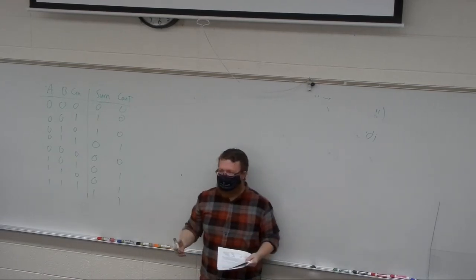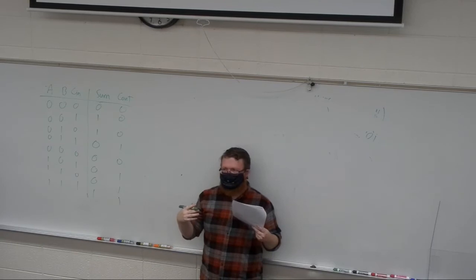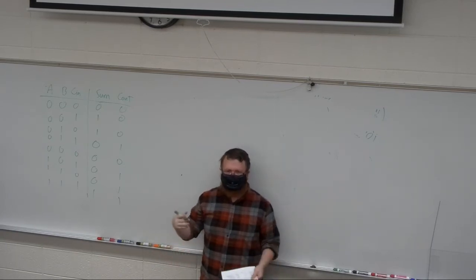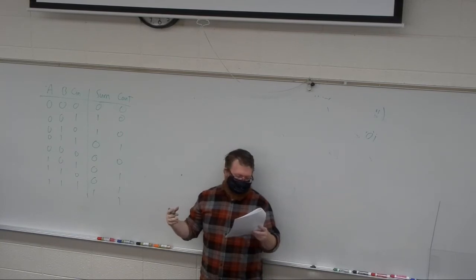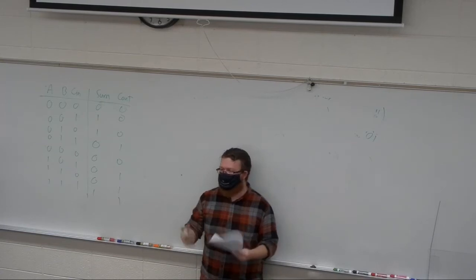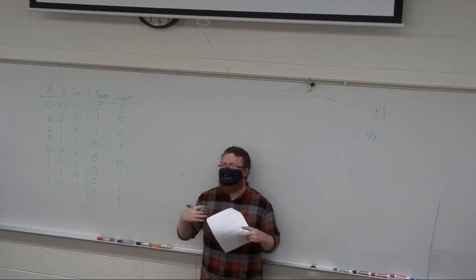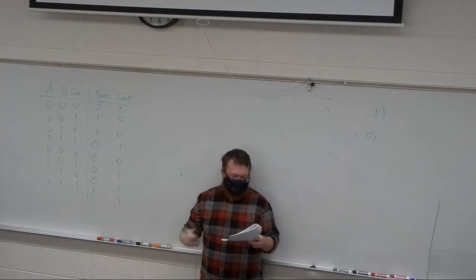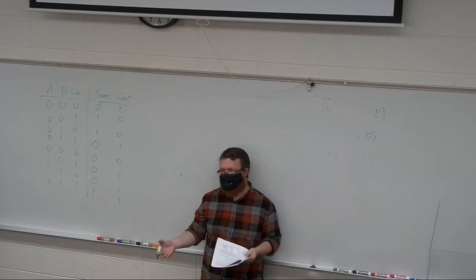So an ALU is the idea where you're going to take adders, subtractors, what else are they putting in there? Complementing and various functions and putting it into one block. And then you're going to be able to pass a command to this block as well as the inputs and get the result that you want. So functions that you might have, right, are like add, or add with a carry, or subtract with a borrow.